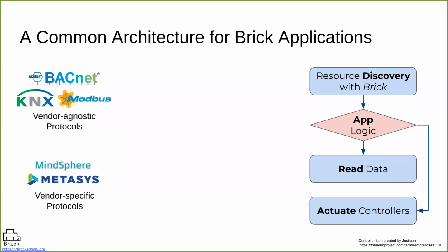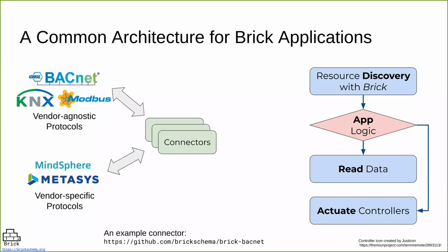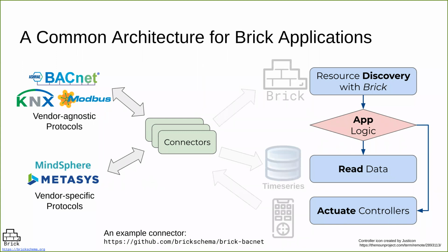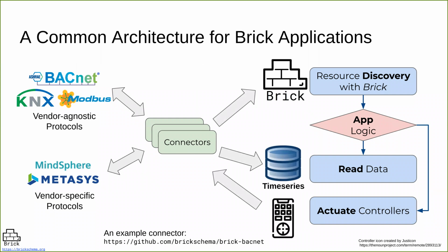Those data may come from various data sources, such as vendor-agnostic protocols like BACnet and Modbus, or vendor-specific interfaces like the Metasys API. Connectors read data from such data sources, and those connectors usually need to be highly customizable across different implementations. You can check our example connector, brickschema.